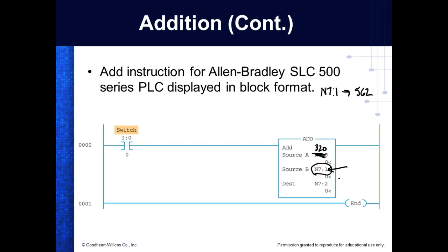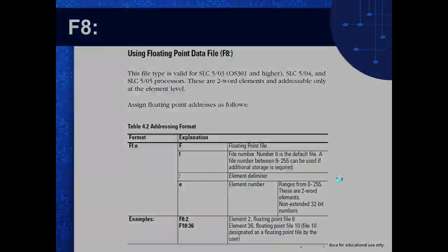Now, how can the contents of this address be? I mean, it could be the results of another math operation. It could be brought in from inputs, right? So that would be considered a what? A variable. Does that make sense? Because we can change that without changing the what? The program. So this would be an example of what we call direct addressing.